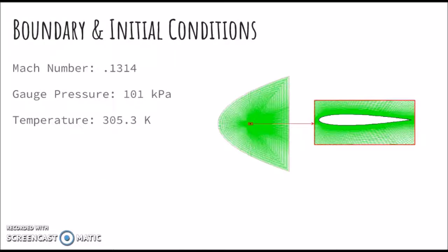In order to compute the fluid flow around the airfoil, a mesh was utilized that had a very high aspect ratio around the boundary layer, but a much smaller aspect ratio at areas away from the airfoil. The high aspect ratio was needed in order to accurately compute the compressible flow. The physics of the domain were modeled as steady and density-based.